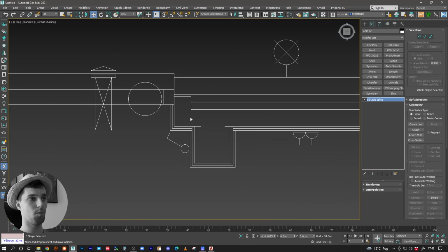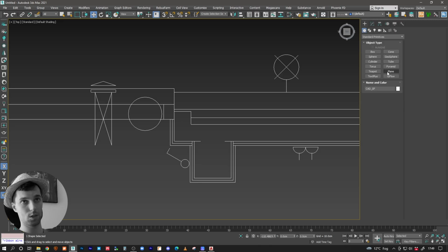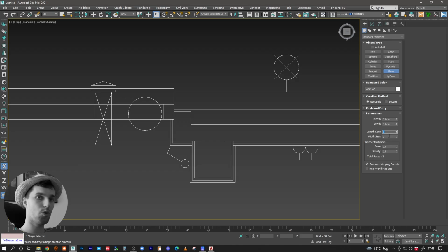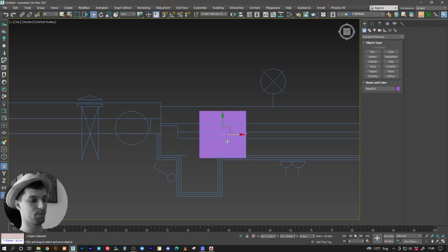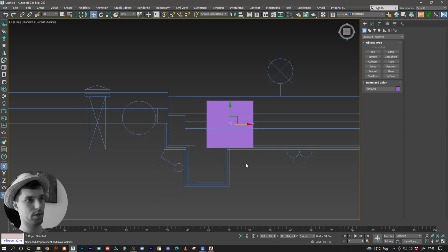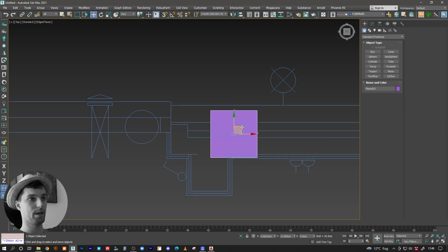So we're going to start modeling this in poly modeling. We're going to use a plane. We're going to use 1, 1. By default, it's usually 4, 4, but just right click there or just put 1, 1 manually, right? And the next thing we're going to do is drag this and enable edges, so we will see the edges. So we're going to press F4, and we're going to press S.